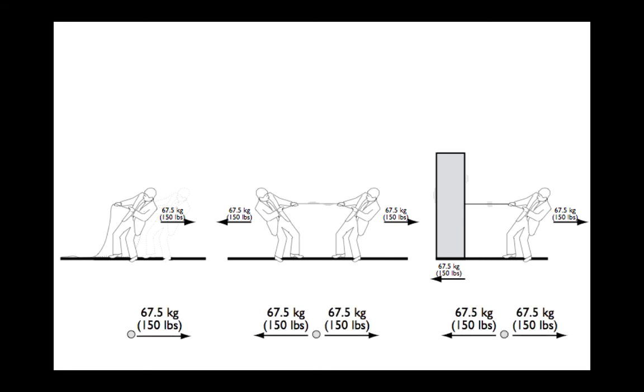Now, when we turn these loads into forces, when we think about these mathematically, remember that we're going to use vector geometry. So every one of these 150-pound forces, we're going to draw as an arrow, and we usually draw these arrows to scale. So 150 pounds is the same length arrow throughout the drawing. If we were doing a 300-pound load, we would double the size of the arrow. 75-pound load, we would halve it. And then we think very carefully about the direction and the sense.